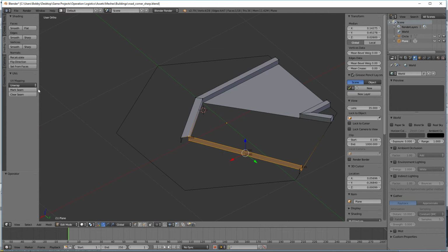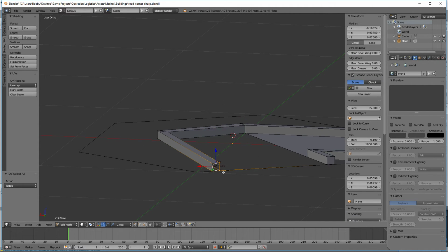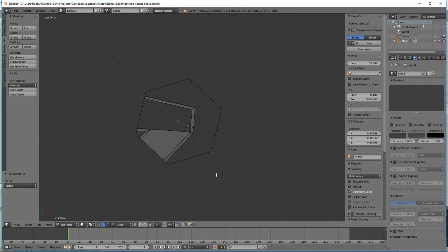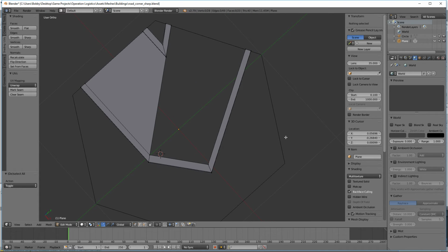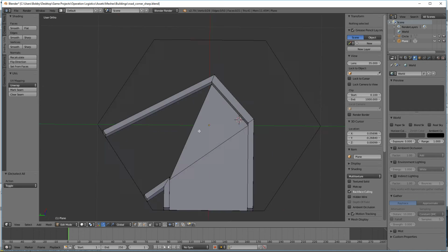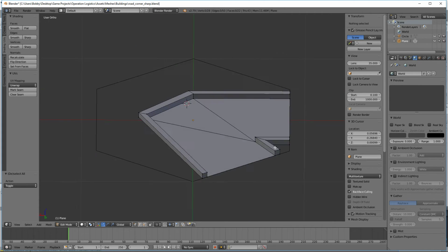This is a very sharp corner indeed. And this one went the wrong direction, so I'm just going to flip direction over there to make sure the normal is correct. Same here, actually. That one needs to be flipped too. Actually, this one does as well. I blame the fact that this one was the wrong way. There we go. Okay, so here we have kind of a curve. It's very, very sharp, but that is kind of to be expected. Okay, so we'll go ahead and do that.